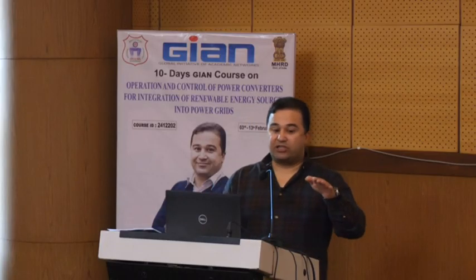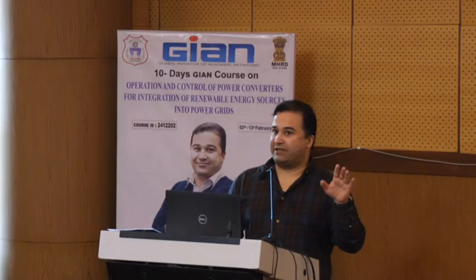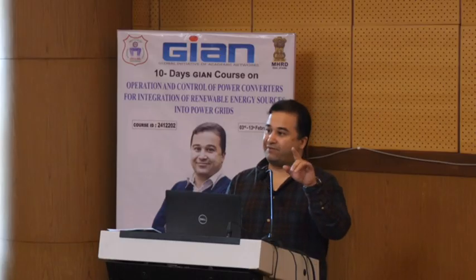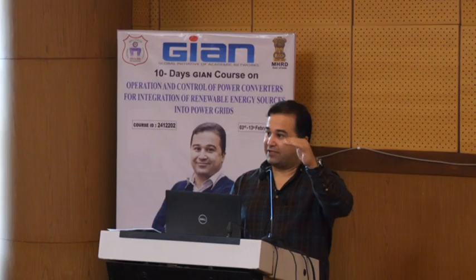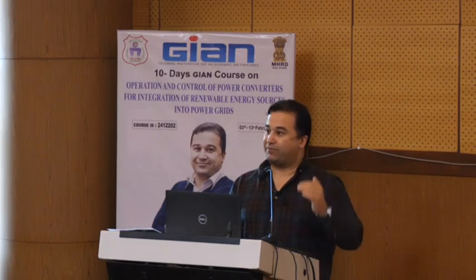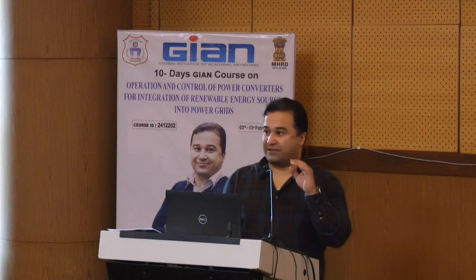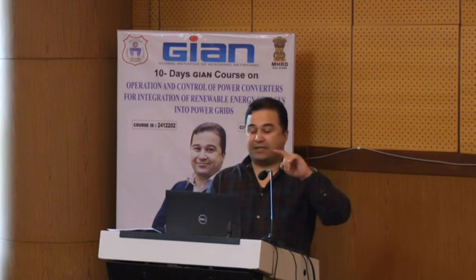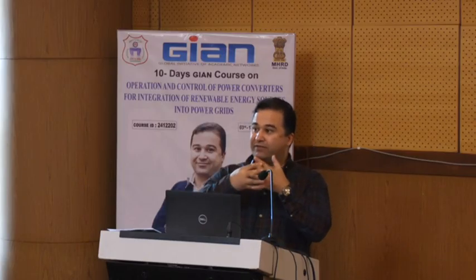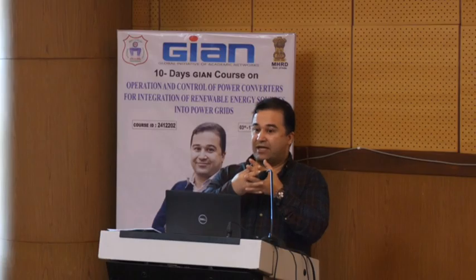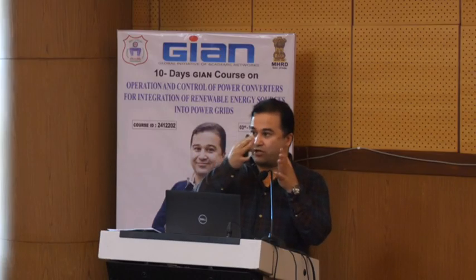So when the radiation changed, I think probably when it reached 35, the radiation at 9 a.m. is different from 10 a.m., 11 a.m. and 1 p.m. So when we reached 35% of the capacity, the second converter connected in parallel with the first one, and when it passed 65, the third one also connected.